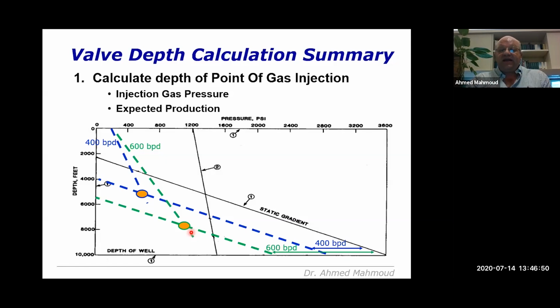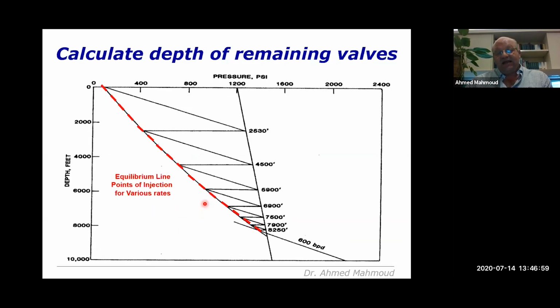And this will take care of the calculation of the points of gas, because now I have 2 gas injection points. And the next thing, I can bring all my points, which I have together, and then I will join them. And when I join them, I will obtain a line, which is my dream line, the line I've been working to draw all the time. And this line will represent flow to the wellhead with positive pressure.